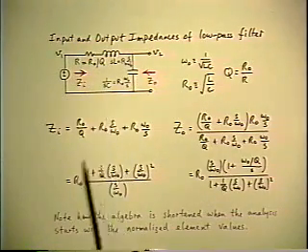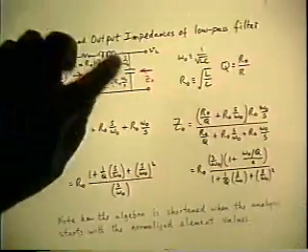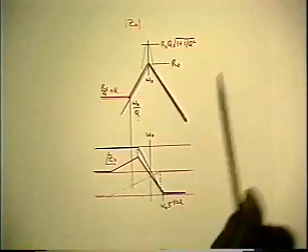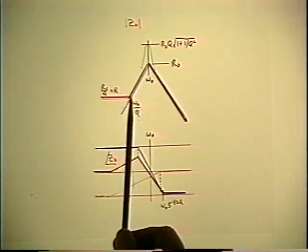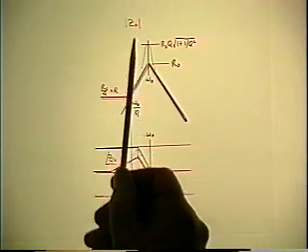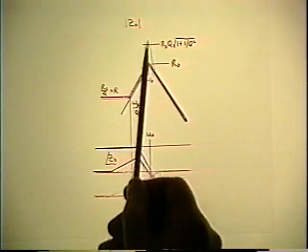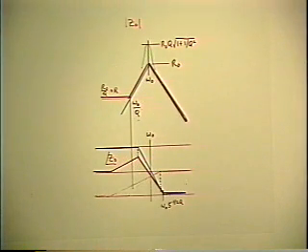That's what you'd expect. So the effect of the resonance is to cause the output impedance to peak up beyond its 0 frequency value, which is what you expect for the effect of the resonance of the RLC.